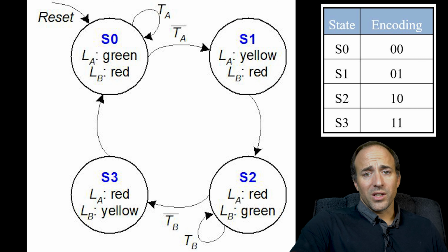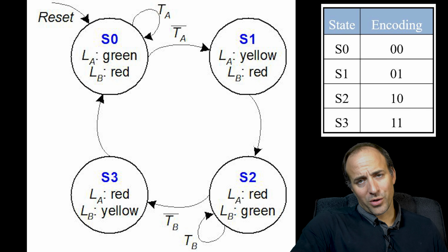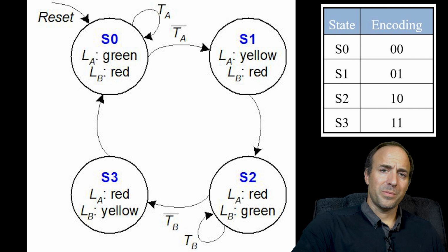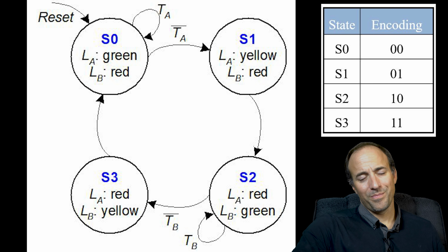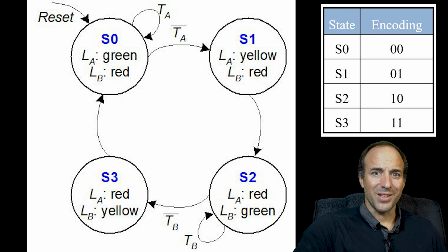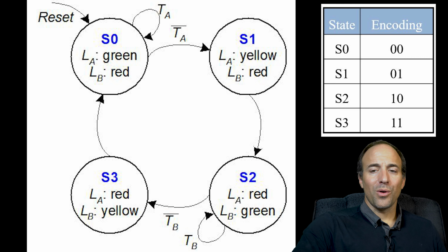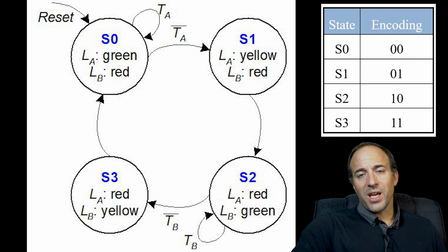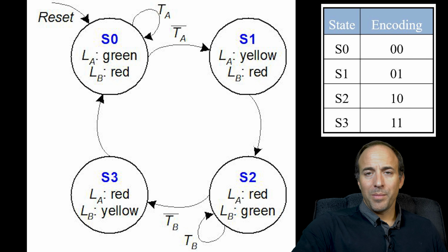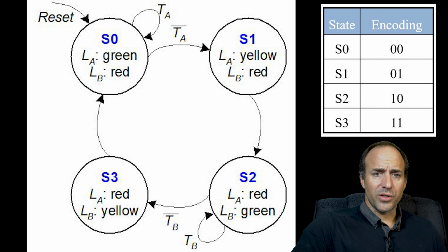Since the reset signal will reset the state register to 0. Of course, unless we use some special type of flip-flop or a non-traditional flip-flop design that doesn't reset to 0. But in general, flip-flops reset to 0. So our state value of zeros will generally be associated with our start state. And we want to ensure that we return to the start state when that happens.